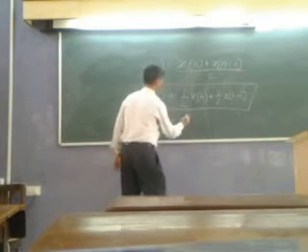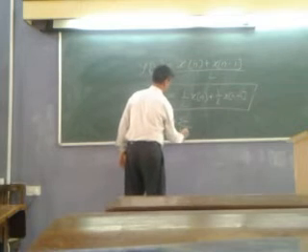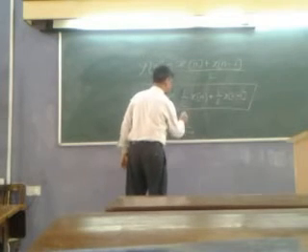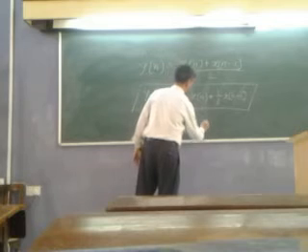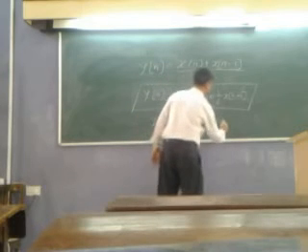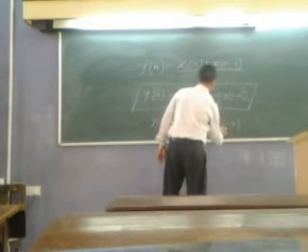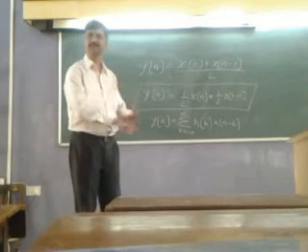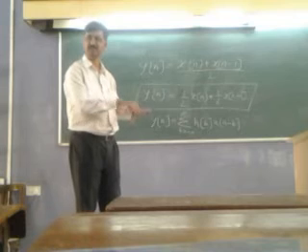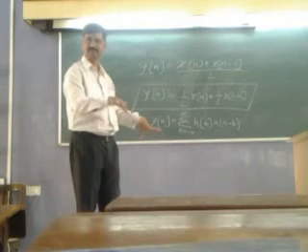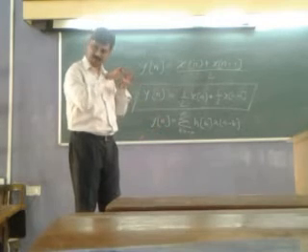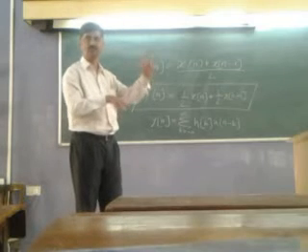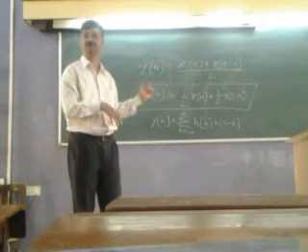Yn is equal to summation k equal to minus infinity to infinity h of k into x of n minus k. Means the convolution equation is also a summation of infinite terms, where each term contains one input and one coefficient.